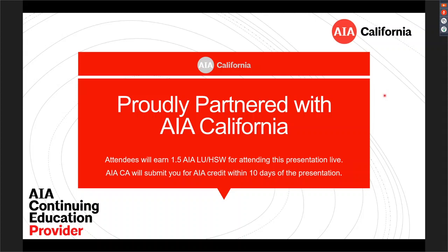Well, NMAs would be providing standard industry details to the drawings, like listings can be added as an NMA. Same with our pre-approved details. I actually have a problem personally with approved with comments being done when you don't have any listings, because now you're approving something you have no idea what it is. But I know for our fire life safety penetration details, there's a general note that says provide these during construction, what's going to be used, and those can be added as, again, it depends on what it is. Unfortunately, I have to say that it depends. That's kind of the famous answer.